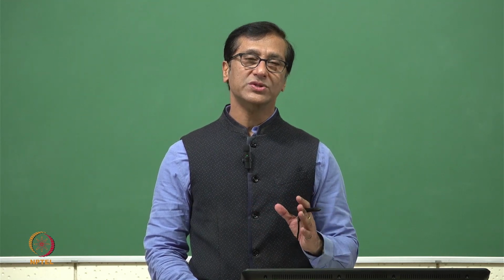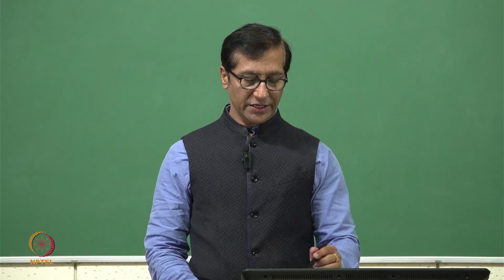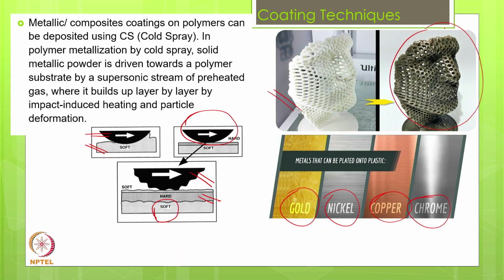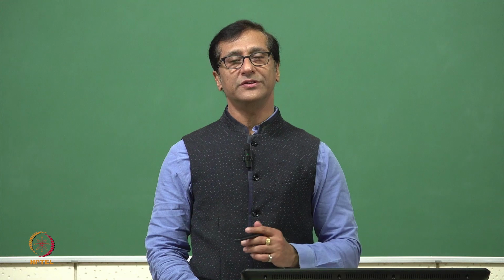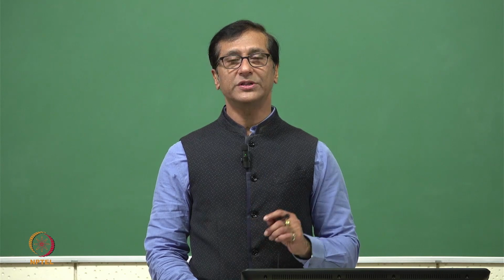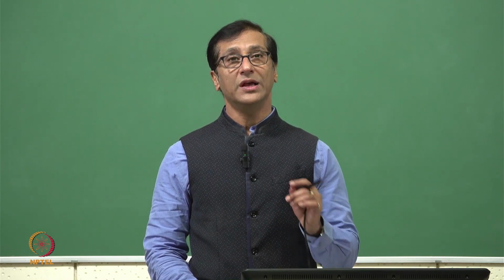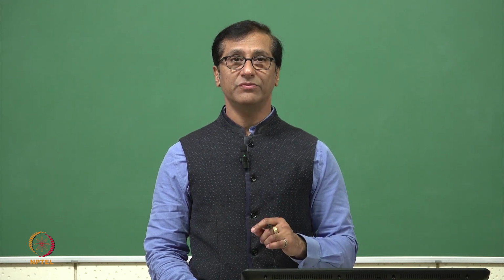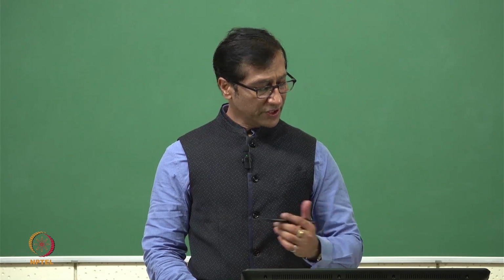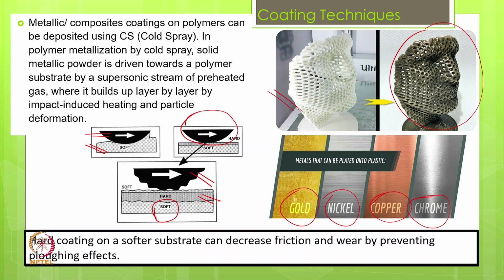If it is only aesthetic, that's a different thing. Here it appears that only the aesthetic is given more weightage, then it is a different thing. But when we come to tribology, we really require load and speed conditions also, and we want a minimum to minimum wear rate to occur. So those things are important, particularly when we are going for the coating selection.